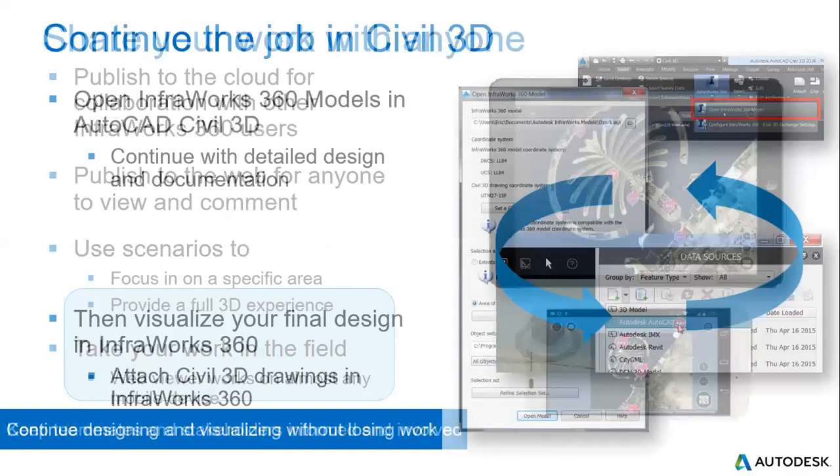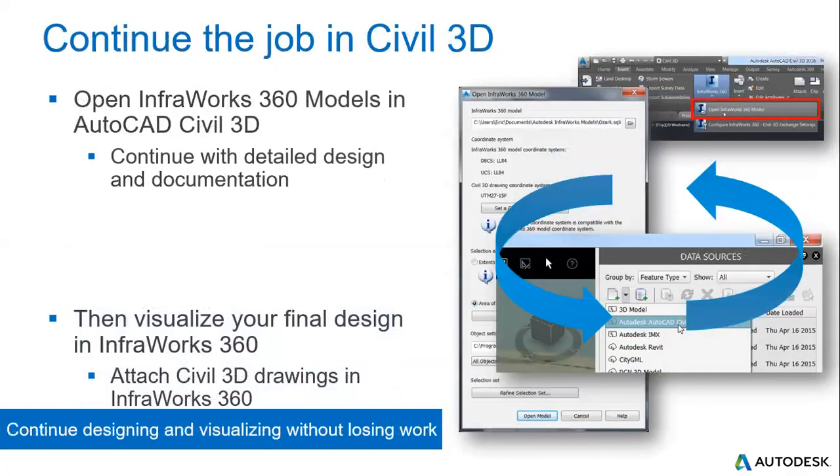So as we had seen earlier, this just shows you how you are able to move from Infraworks to Civil 3D. Notice that at the top right corner, you have the Civil 3D window, and via the insert menu, you should be able to open an Infraworks model. You are able to adjust the information that you want imported.